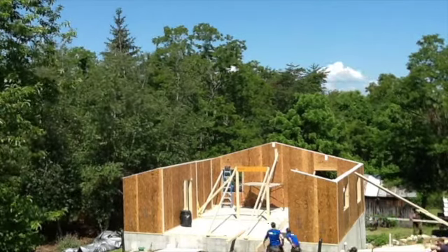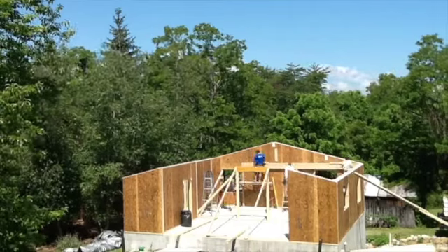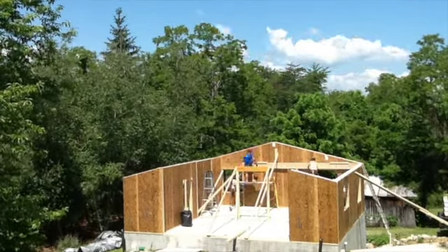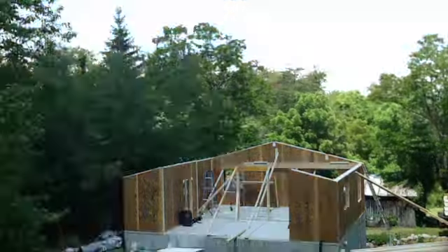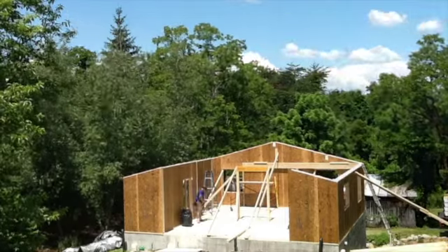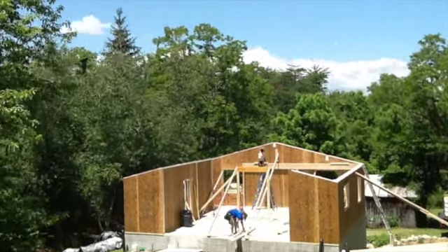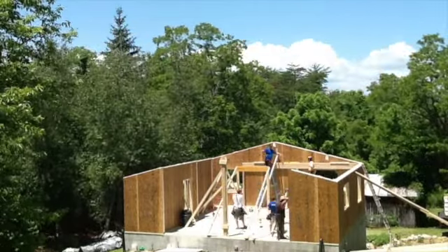So this is basically a 3-room apartment. There goes one of the parallam beams that's supporting the loads of the building and transferring it. Right below where they're working are 2 garage doors, and so the loads from the roof have to be transferred over to the sides of the building where they can be borne without bringing down the garage door openings.